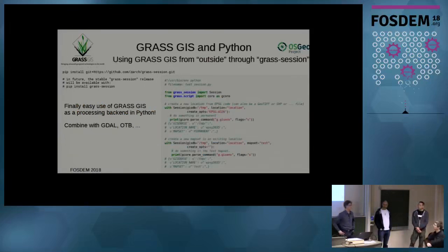Just to tell you, GRASS comes naturally with a Python interface. This Python interface has been simplified recently, with something called GRASS session. You can use it just to initiate your session, which means in a few lines, like with GRASS session and so on, you can create it, and then you can just go ahead and do your analysis. So nothing complicated, and like other software projects, you can go through and load your data set. It is internally using, as before, the GRASS GIS database. But if you work like this, you do not really have to think too much about it. What you do have to know is, of course, what the projection is and other stuff like that. But this session manager is doing it all for you.